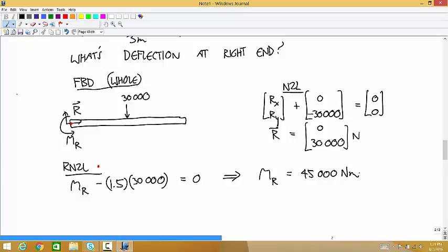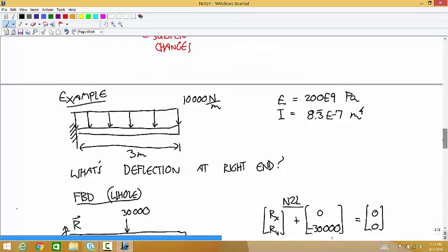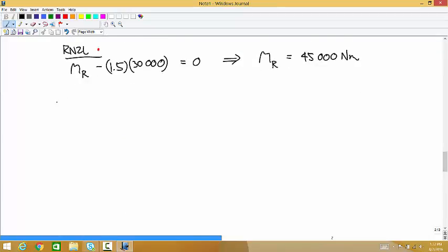And now how many cuts do we have to make? So if you look at this picture that's up, it'll screw you up. You need to look back at the original picture. So there's the two endpoints. Are there any places between the two endpoints where that distributed load changes or point forces or anything? No, so we're just going to do one cut. Okay, so cut 1 represents all x values between 0 and 3.